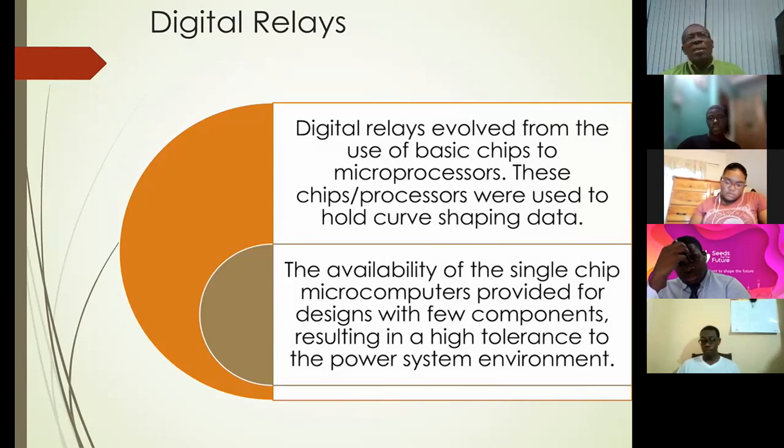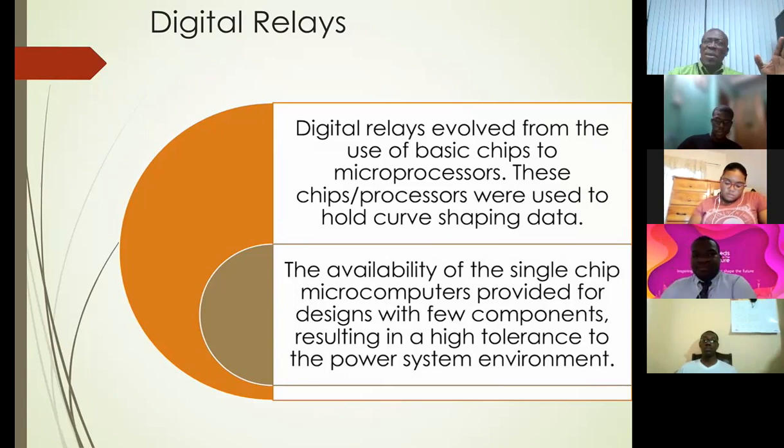If I was using a standard inverse for my electromechanical, I would have to change out the relays if I were using extremely inverse before. But now I can buy one set of relays, and if I want extremely inverse, or if I want standard, I can make the selection. A lot more robust than the analog.